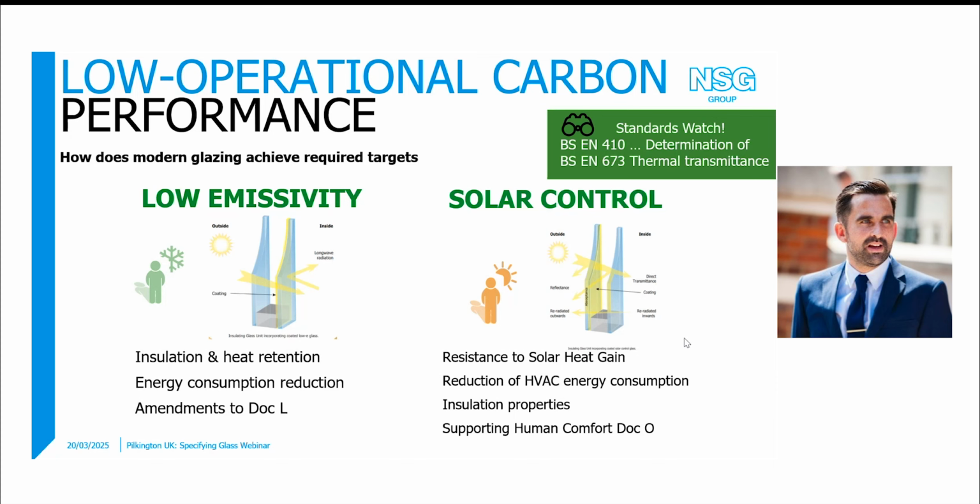For high performance and for low U values, an offline coated low E product should be used, such as Pilkington Optitherm S1, which will arrive at a 1.0 center pane U value, for example. Low E coatings, it's worth pointing out, are designed to intentionally allow a degree of passive heat gain into the space. So they therefore will be used in passive house projects.